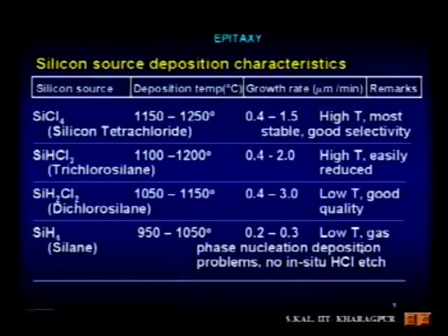But if you compare this table, the important feature of the pyrolysis reaction is low temperature. That is why somebody says that epitaxial growth by pyrolysis appears to become the most widely applied growth technology in the future. The reactant species for pyrolysis reactions are either hydrides or organometallic compounds.